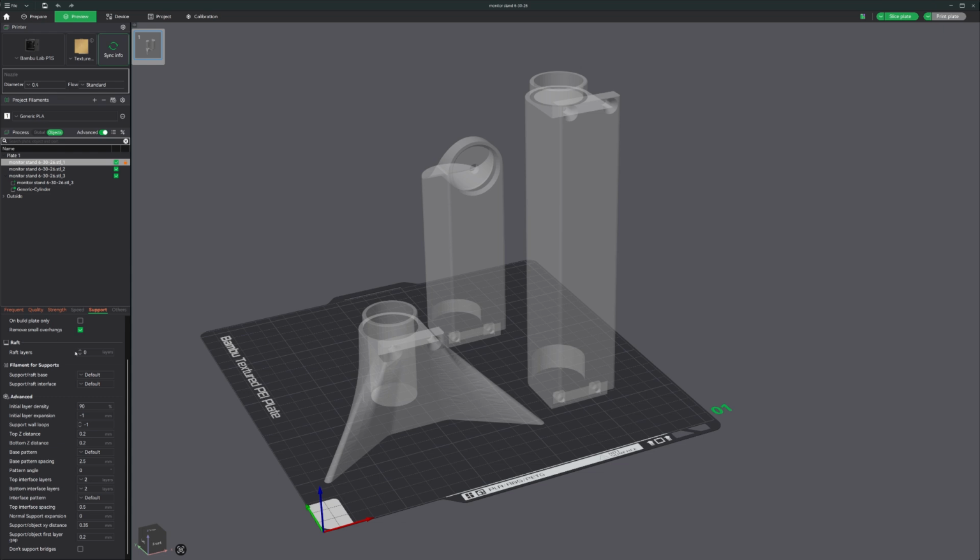The benefit to doing this is having a really good finish on your part if you have enough surface area where the support's going to be. That's the downside I've noticed: if you don't have enough surface area on your top part, let's say it's PLA and your interface layer is going to be PETG, since they don't fuse together, it won't adhere, and you might have a print failure because of that. So if you ever do this, just make sure that you're using it for places where you're going to have a significant amount of interfacing between the PETG and your PLA.